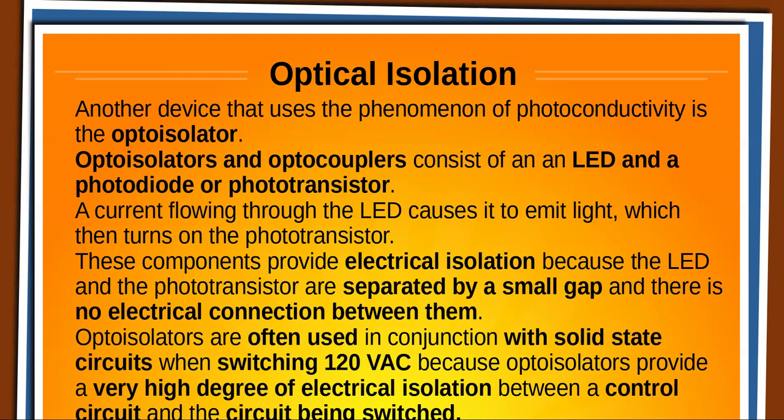The main reason for having them electrically isolated or physically separated is so that you can potentially, and we'll talk about the relays, control a very high voltage or high current that's isolated from the control circuit, which could just be 5 volts or 3 volts or something. When you're talking very high voltages, you definitely want to keep that isolated from your control circuit. And normally you're going to see, in what they call solid state relays, are built this way. And normally they'll take 5 or 12 volts in and will control 120 volt AC.